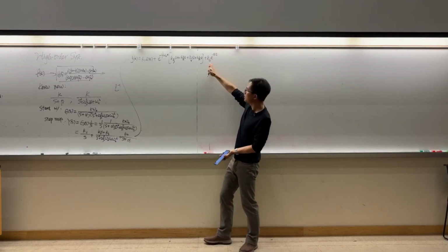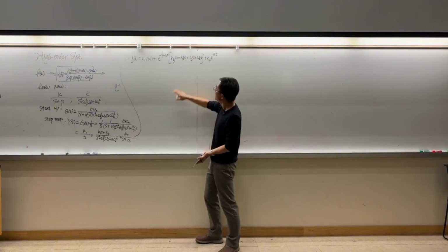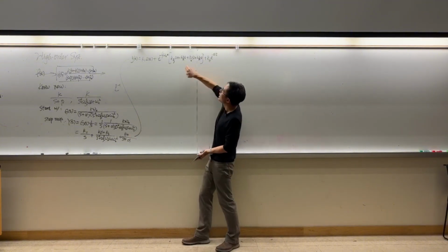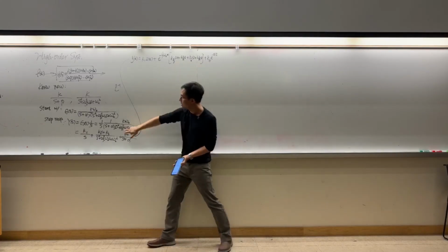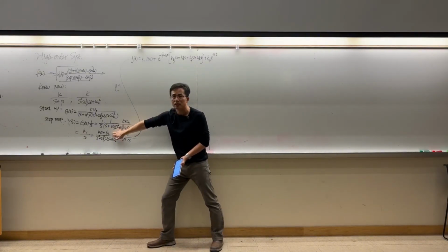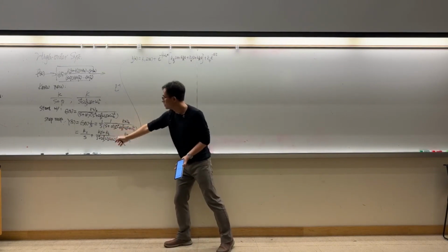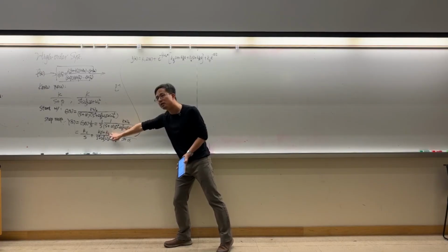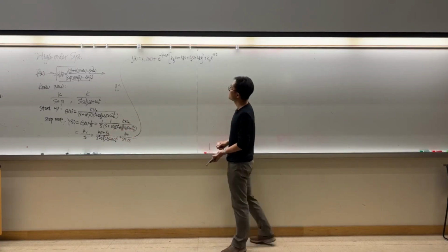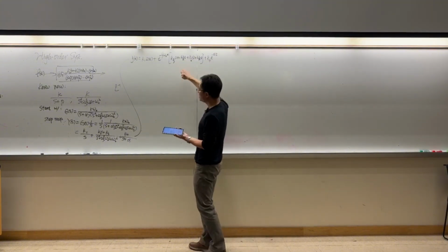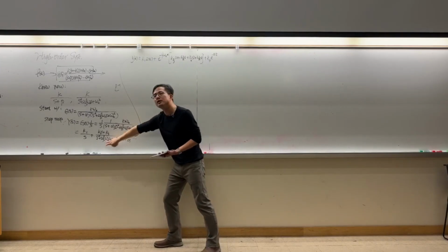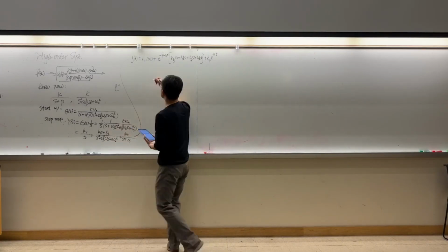so first order goes to e to the negative alpha t. Coefficients don't change. K4 is the same as K4 here. And in the middle, we have sinusoidal components. And I used K5 and K6 to indicate that they may not necessarily be the same as these K2 and K3, because we have to decompose this into sine and cosine Laplace transforms. But the structure is like this. So if we plot the locations of the poles, it's going to look like this.